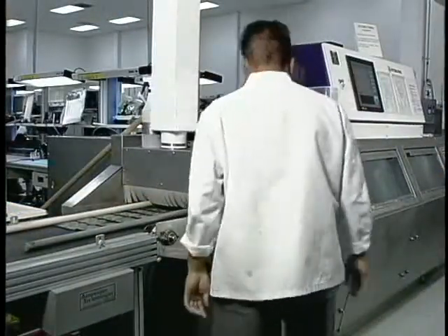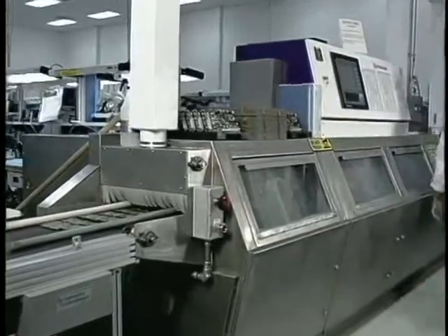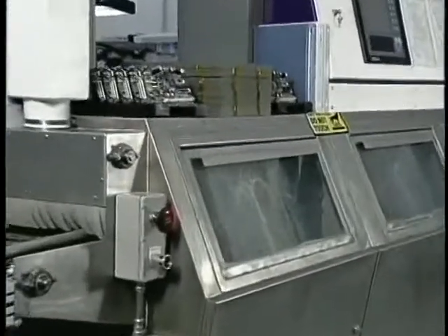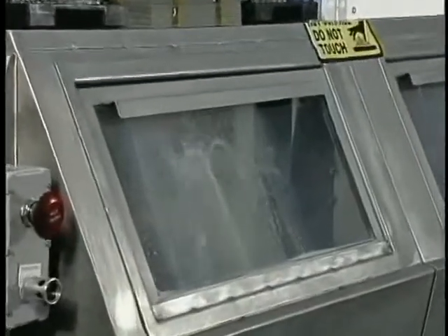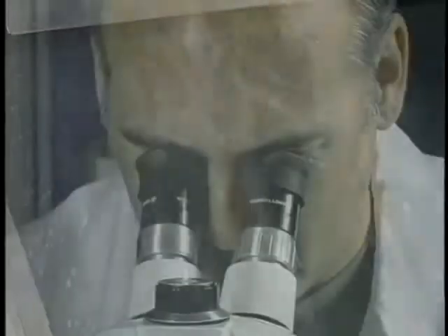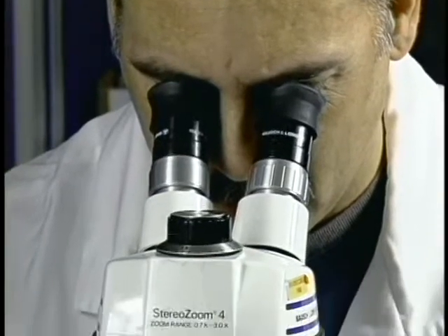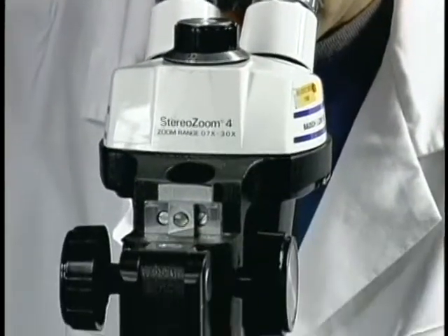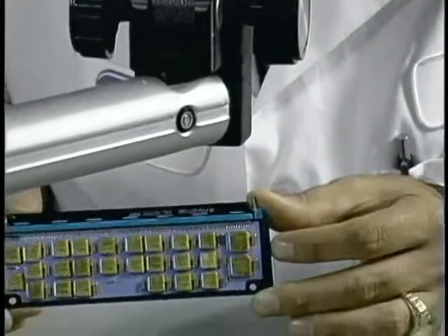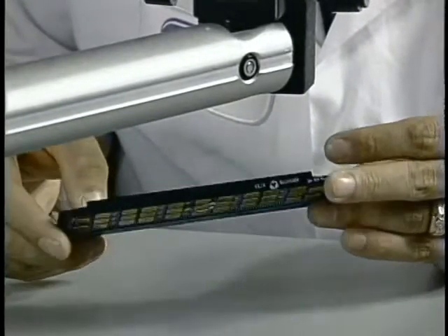The assemblies are usually cleaned to remove any flux residues which can degrade the assembly if they are left on. When companies use low residue fluxes, the cleaning operation may not be necessary. A visual and/or microscopic inspection is often done to identify areas where there is not enough solder, where there is bridging between the solder joints or other soldering defects.